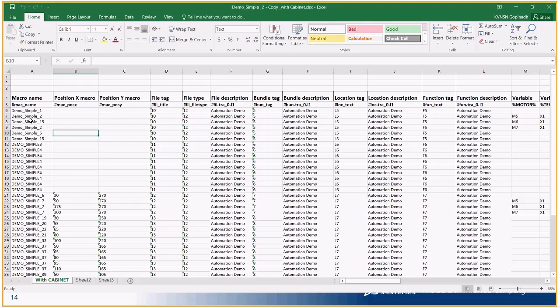So as you see, for XLS automation, the user has to configure the XLS sheet with the device data, manufacturing part numbers, and the macro references. So this is the macro reference table where I have different macros. As I said, a macro is a single symbol or a group of symbols associated with the manufacturing parts, linked together with any kind of automation process.